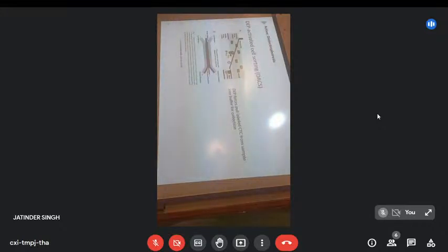A lot of the slides in today's lectures will be sorting one kind of particle from another. That's what you do with particle separation. So we've got the sample flow coming in here, which contains two types of particles. Some of them experience a force going down, a dielectrophoretic force in the asymmetric field.